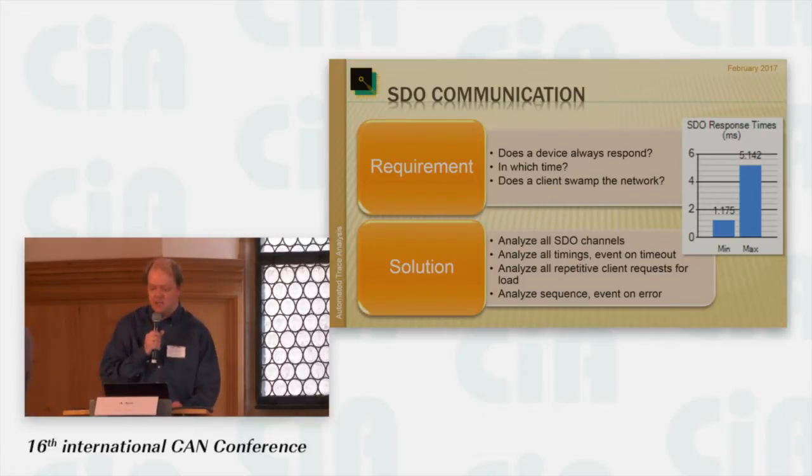We can also check if there are aborts and mistakes in the protocol implementation, and by understanding the SDO protocol, we can keep track of the size of the largest block transfers, and such information allows a systems tester to better understand network behavior.